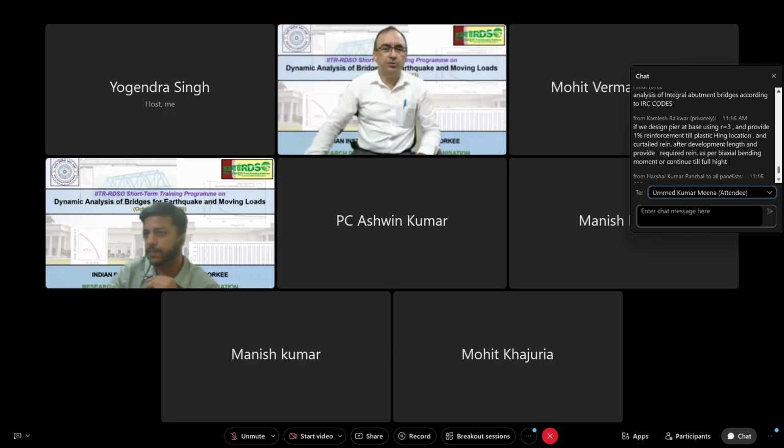Yeah, so what is the question? I mean, perhaps they want to know whether this is okay or not. Right. Means should we provide the reinforcement that we are getting at the plastic hinge location to the full height, or we can just curtail it after development? Now, that's what I explained.